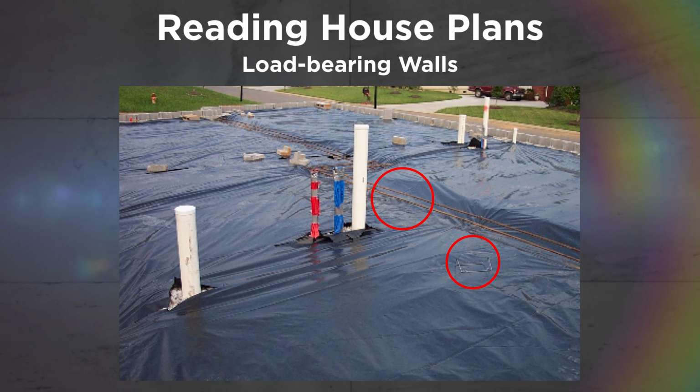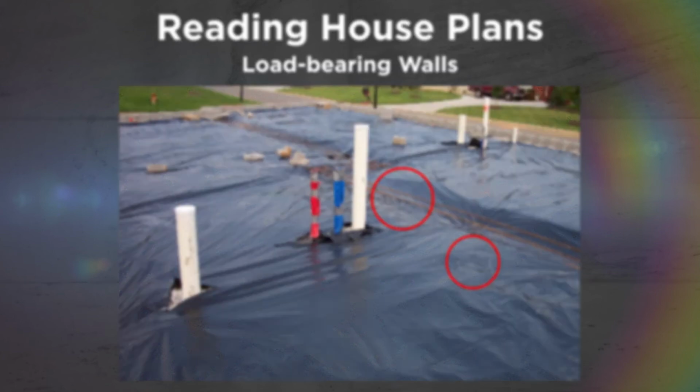In one circle, you will see the recessed area and rebar following the direction of the trench. In the second circled area, if you look closely, you'll notice a wire support that will lift the rebar out of the bottom of the trench to allow concrete to fully encase the two sections of rebar.